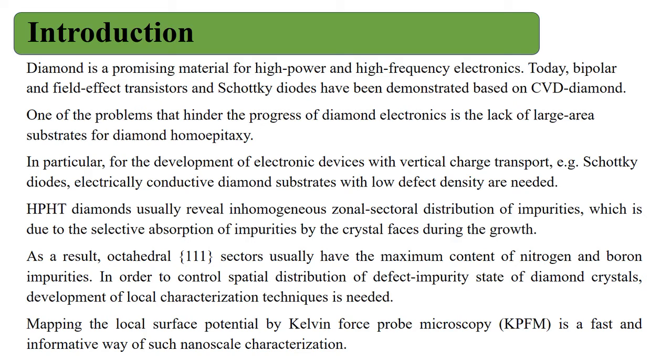Today, bipolar and field effect transistors and Schottky diodes have been demonstrated based on CVD diamond. One of the problems that hinders the progress of diamond electronics is the lack of large area substrates for diamond homoepitaxy. In particular, for the development of electronic devices with vertical charge transport, e.g. Schottky diodes, electrically conductive diamond substrates with low defect density are needed.